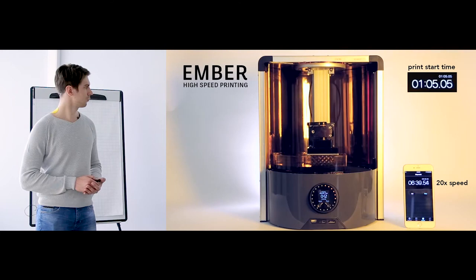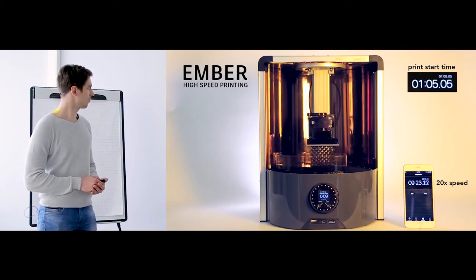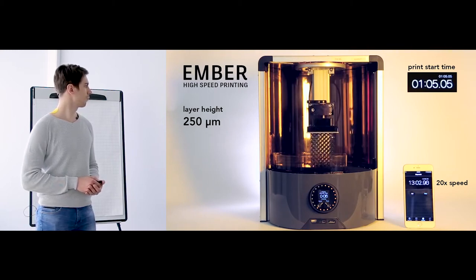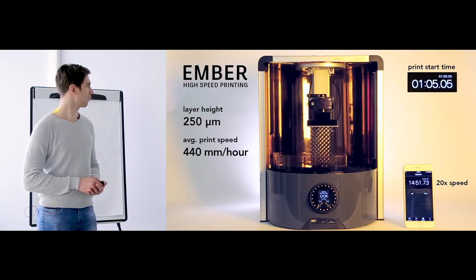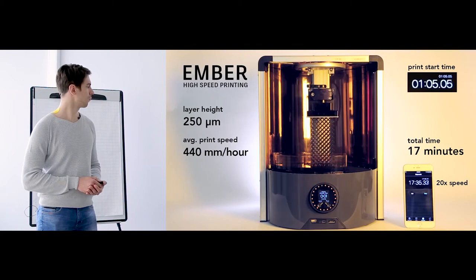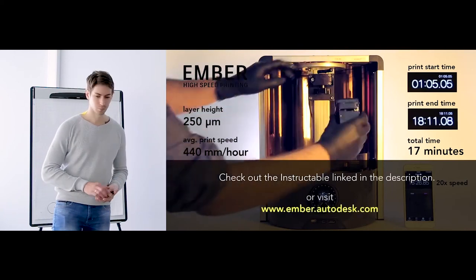This part is printing 24 times faster than a print using the standard Ember resins and print settings. The resin is specifically formulated to print thick layers, here 250 microns. Thick layers are difficult to print on stereolithography printers because the light must penetrate deep into the resin without scattering and curing adjacent negative space areas. It prints at about 440 millimeters an hour. This high-speed printing is a great way to get a quick prototype in minutes that would typically take several hours. After about 17 minutes, the print, which takes up the entire build volume of the printer, is complete. Check out the Instructable linked in the description to learn more, or visit ember.autodesk.com.